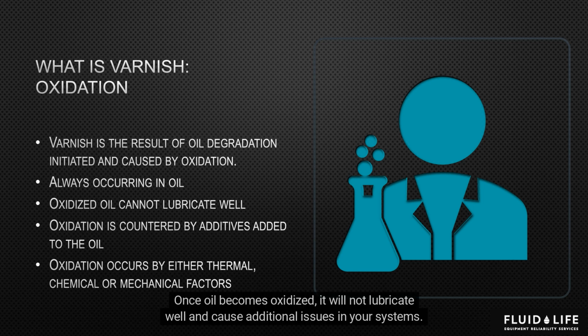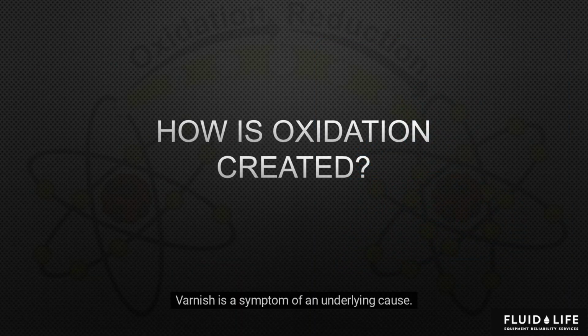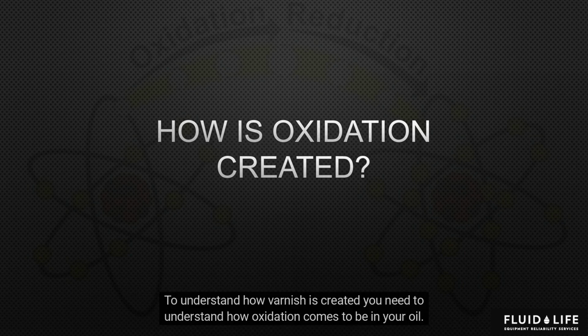Once oil becomes oxidized, it will not lubricate well and cause additional issues in your systems. Varnish is a symptom of an underlying cause, that cause being oxidation of the oil. To understand how varnish is created, you need to understand how oxidation comes to be in your oil.